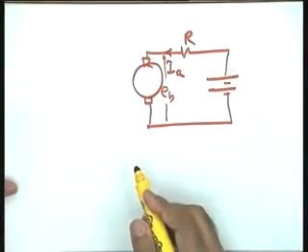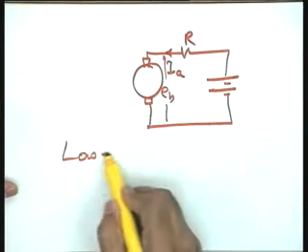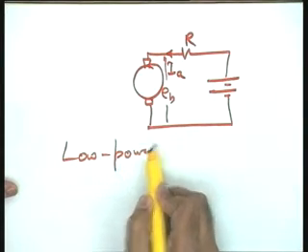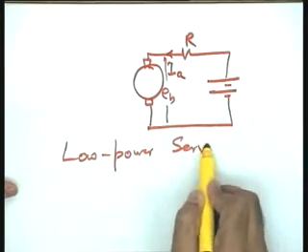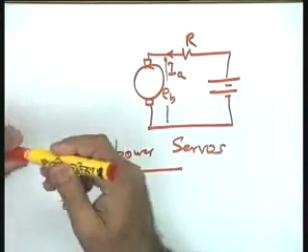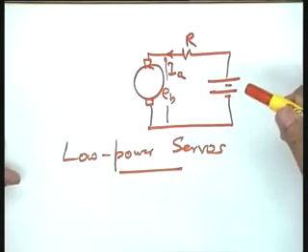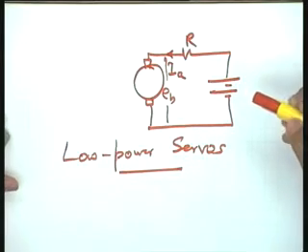Therefore I can conclude my discussion with the statement that the field controlled motor is a good competitor for selection as far as low power servos are concerned. Wherever there is a low power requirement, so that the armature current IA will be low, it will be possible to maintain that current at a constant value reasonably well.